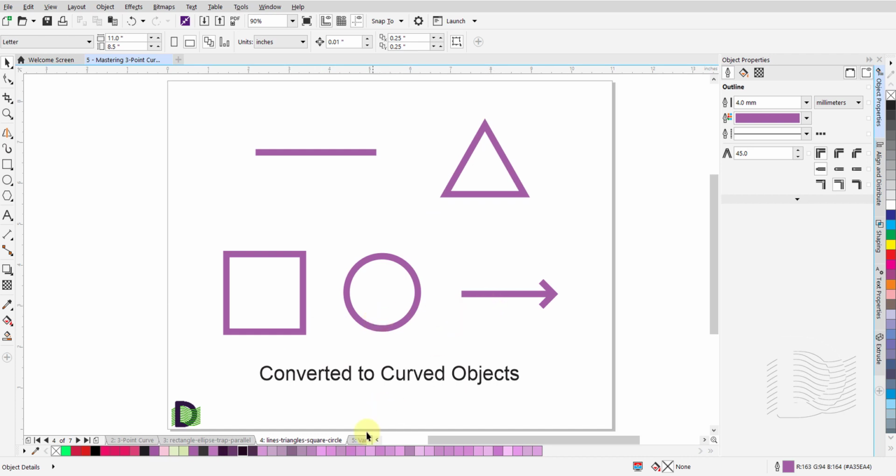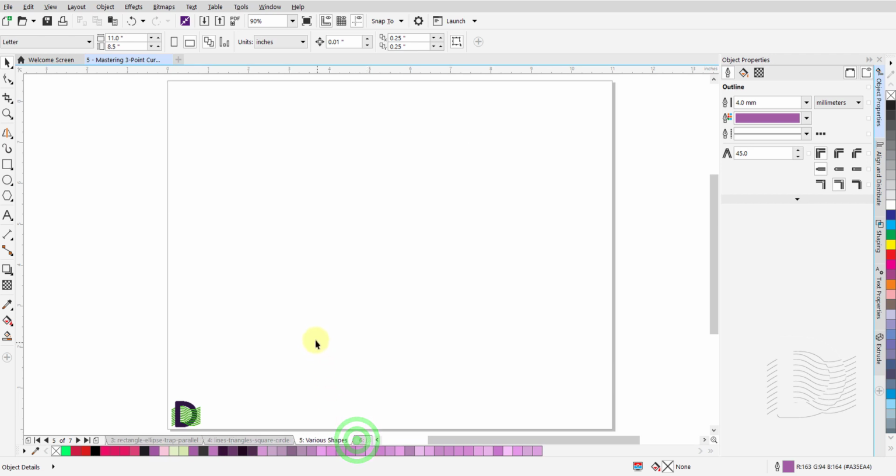When you draw strokes that are to be converted to any of the above objects, remember there is a time elapse between the time you finish your strokes and the shape recognition to take effect. For example, if you set the timer to 1 second and you draw a triangle, shape recognition will take effect 1 second after you finish drawing the triangle. 1 second setting for the elapsed time is the default setting in CorelDRAW.